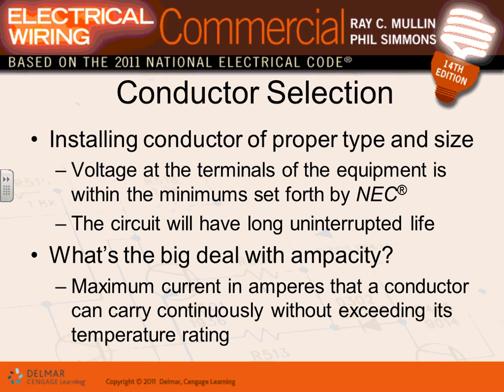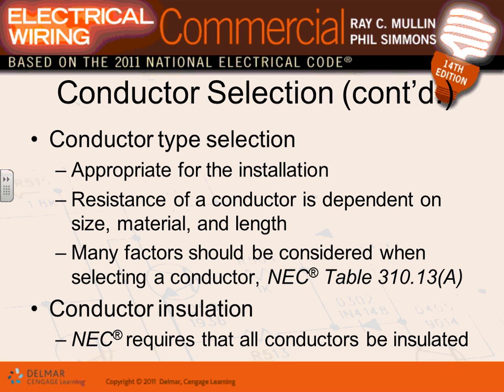So why it's a big deal for branch circuits, like I showed you at number 12, you do not want to exceed what the conductor can carry. The capacity of a conductor is defined as the maximum continuous current that the conductor can carry under its specified conditions. Like we said, the maximum for number 12 under the conditions that we put it in was what? 15 amps.